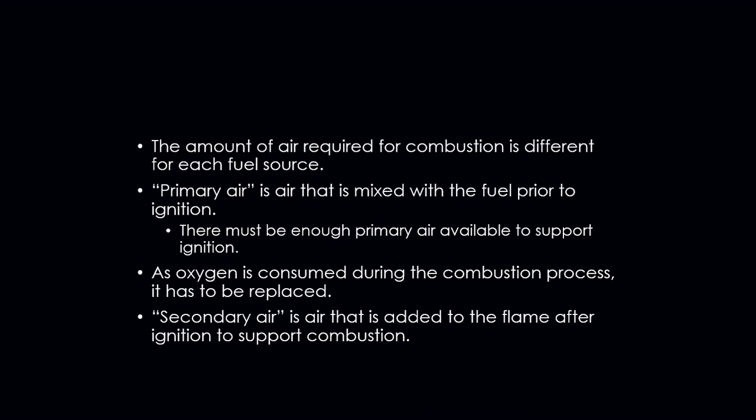The amount of air required for combustion is different for each fuel source. Again, go back to the way different gases are constructed, the different molecules. Primary air is the air that is mixed with the fuel prior to ignition. So there must be enough primary air available to support ignition. Any oxygen that is consumed during the combustion process must be replaced. If we're using it, we have to have the ability to replace that air that is being used.